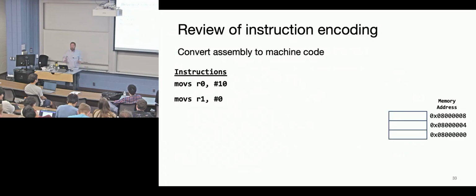And we're not going to go through every instruction. It's not possible. We're trying to give you the general layout of how to interpret instructions and what you need to know. So here we have some MOVS. So MOV is an instruction. It's going to take something like an immediate here. So pound 10 defines an immediate. This is in decimal form. You would have to do 0x for hex or 0b for binary. At least that's how we would denote it here. Most IDEs will do that. And now we're going to move 10 into the register R0.